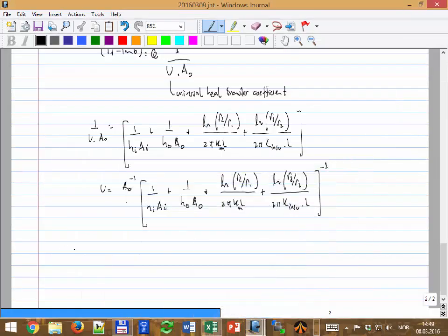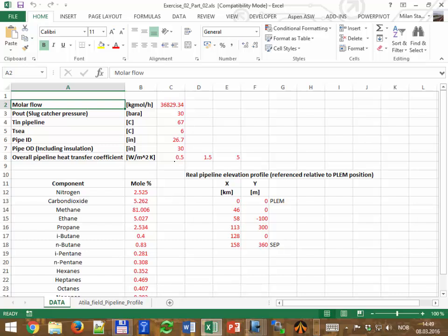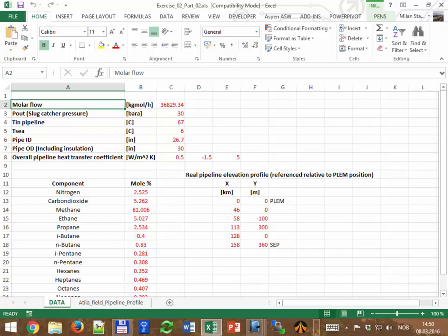So, short on that, the values that I have provided in the Excel file, we are giving 3 values. One of them, 5, is a value that is quite realistic. It's something that you can get with the insulation that I gave you. 5, 4, 3 is quite realistic. 1.5 is already a very low value, which means you have to pay a lot of money, maybe you will have a very bulky system, or a lot of layers of insulation, which is not very practical for transportation, for flotation, etc. Or you have to pay for very good materials that really keep the heat very well.